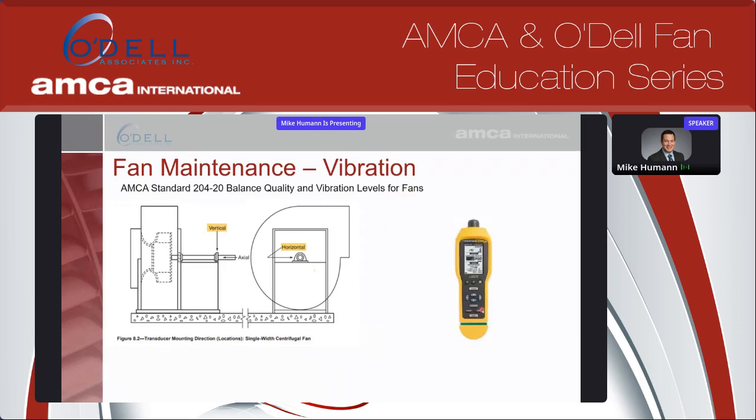And you can also use a vibration pen. Not all fans are set up for vibration monitoring, but you can certainly use a vibration pen and go around and put that on vertically or horizontally on the bearings to help you monitor that, so you can still take readings, even though you may not be sending signals back to a PLC or collecting data. But you can certainly trend data still and grab some instant readings to make sure your machinery health overall is good.